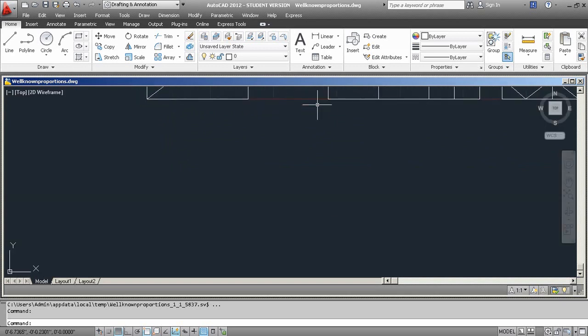Okay, now we're going to make ourselves a room. We're going to start with the line command, and more or less in the middle of the lower left hand corner of the screen, you're going to select a point by clicking with the left mouse button, and then you're going to enter at, which is shift 2. That's going to be a 4-inch horizontal line, so type 4, angle bracket or left chevron mark, and then type 0 because you're going east.